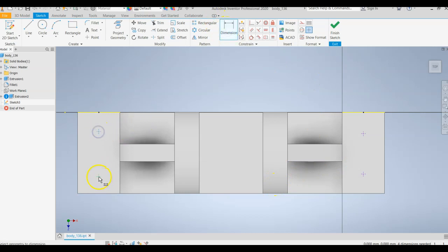Well, if they're 24, let's make them 24 millimeters apart from each other. And let's do a little trick here. I'm going to click the line tool and connect the 2 points on both sides. Oops. Let's try that again. Make sure you snap on the points. Okay, so that line should be locked in with the points. Now let's horizontally align the midpoint with the line. And yep, that's what we want. Okay, so they're vertically aligned and they're horizontally aligned, and they're 24 millimeters apart.